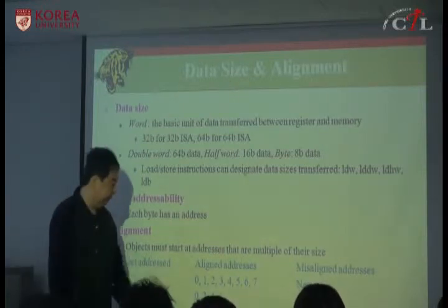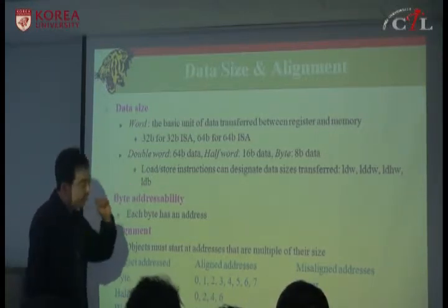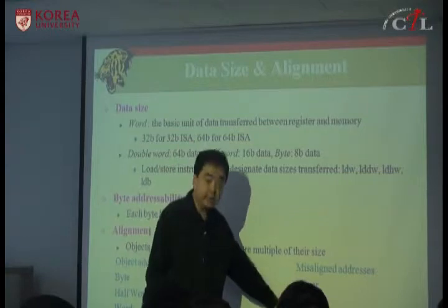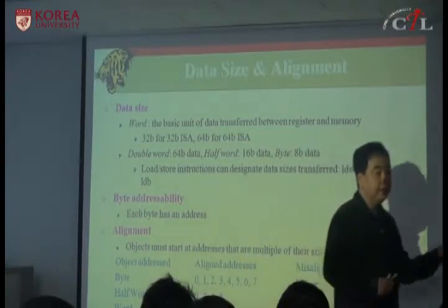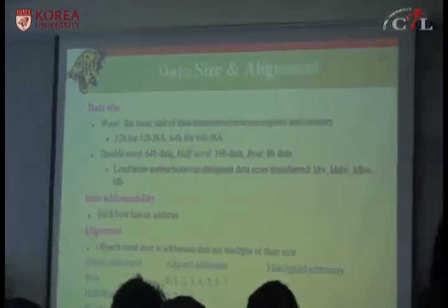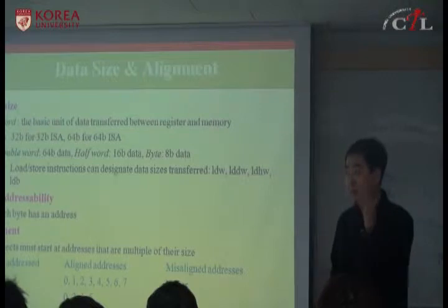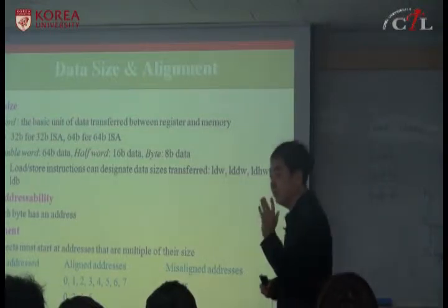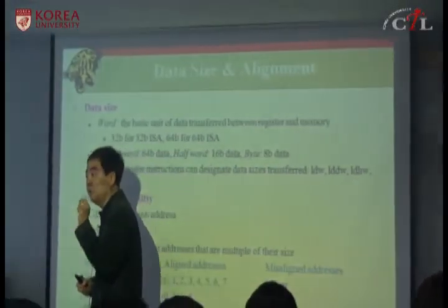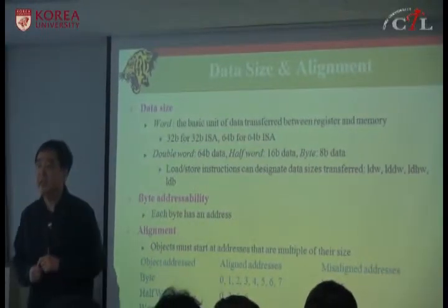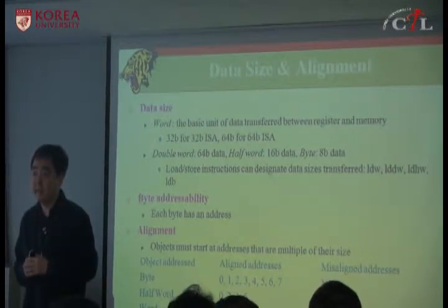And so if the processor generates a misaligned address, say we are trying to load some integer data, the address should be a multiple of 4, right? Like 1000 or 1024. But if you generate a misaligned address such as 1023, it can be a fault, which means your program is wrong and it should be terminated.